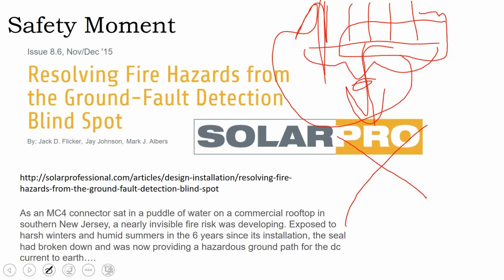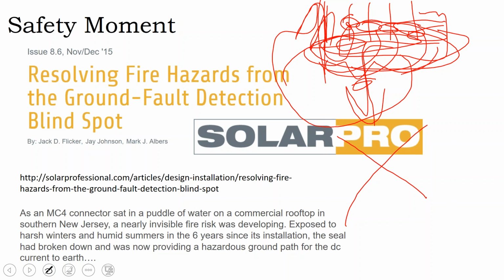And depending on how that fault occurs, if it doesn't occur all at once, what might happen is that one module fails and it backflows into one current, and it's not enough to trigger any alarms. But it's failing because this box is being pulled apart by thermal expansion, and all of a sudden we have a situation with cascading failures that are slowly elevating not just our neutral voltage, but also our ground reference, and it's not triggering the ground fault detection.